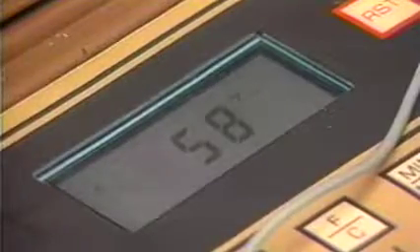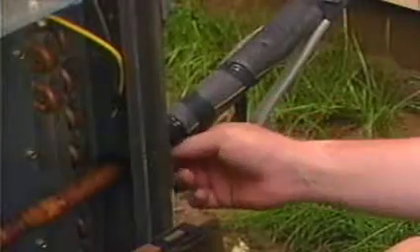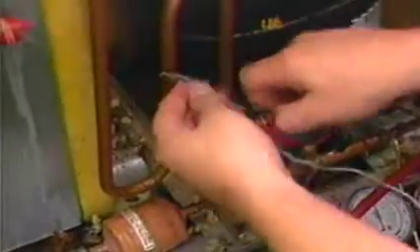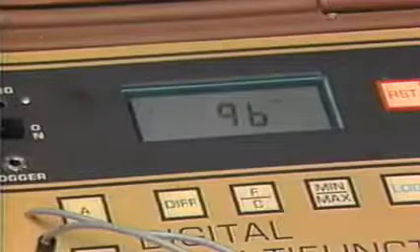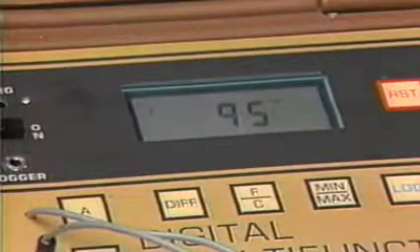The suction gas might be part liquid if the filters are stopped up or the evaporator coil is dirty. The temperature of the discharge line might indicate that there is a problem inside the compressor. If there is an internal refrigerant leak from the high pressure side to the low pressure side, the discharge gas temperature will rise above normal. A liquid line temperature check will determine the subcooling efficiency of the condenser.